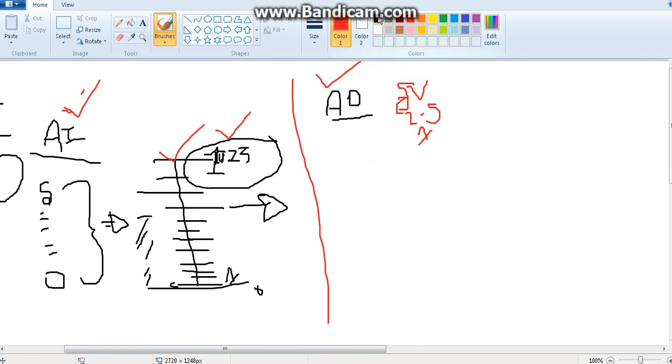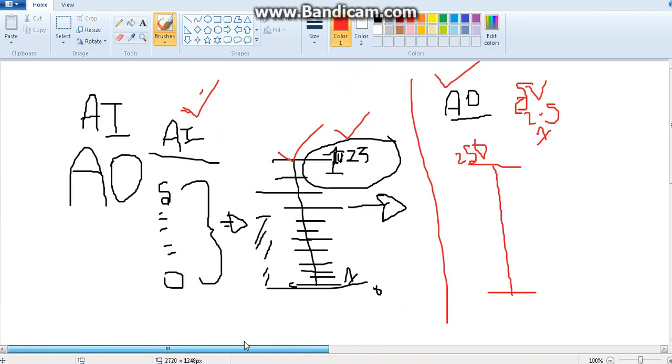Arduino has a different scale for analog output, and that scale has only 256 units. So it is 1024 units when it comes to input, but only 256 units when it comes to output. The maximum value will be 255 and the minimum value is going to be 0, because 256 units starting from 0 means the minimum value is 0 and the maximum value is 255.